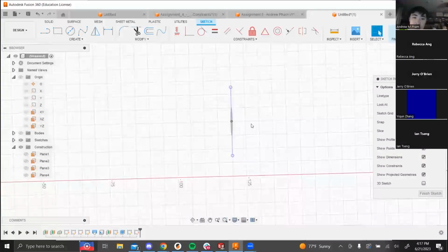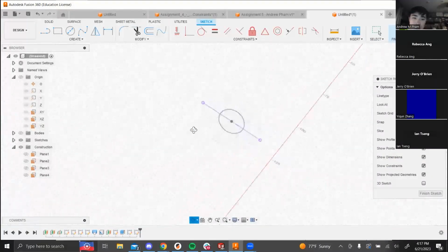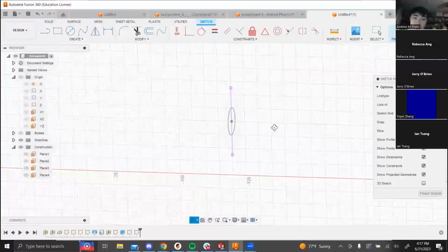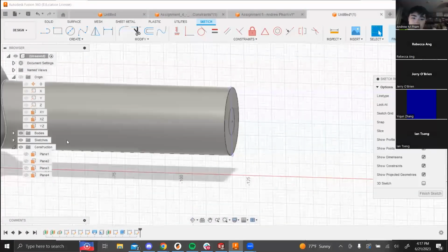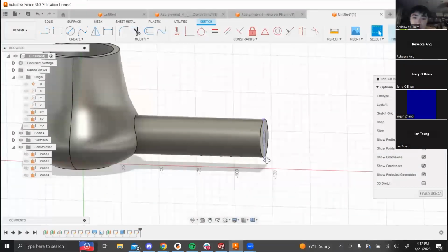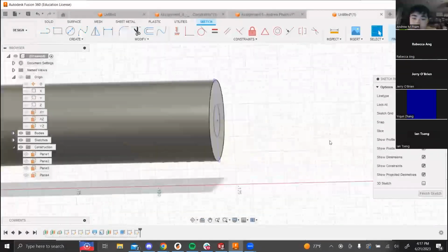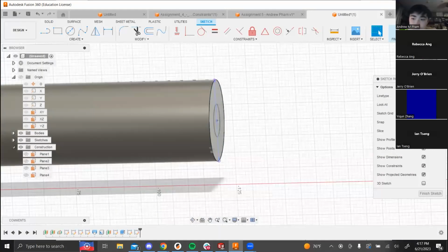You can see this purple line, right? That purple line is the line that we projected from the end of this handle, and we can reference that to make our wire. So now we can draw our wire, and what I want to do before this is make sure this projected line is construction, so it won't be referenced when making a spline. So if you see, I clicked on the line over here, and click construction, and now it's a dashed line. That's what we want.